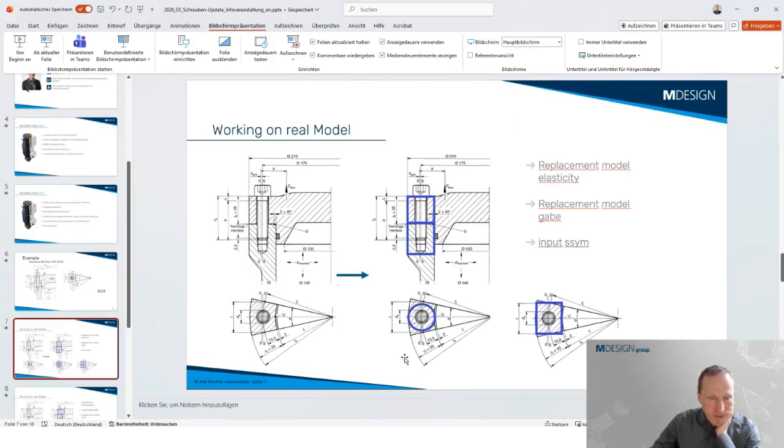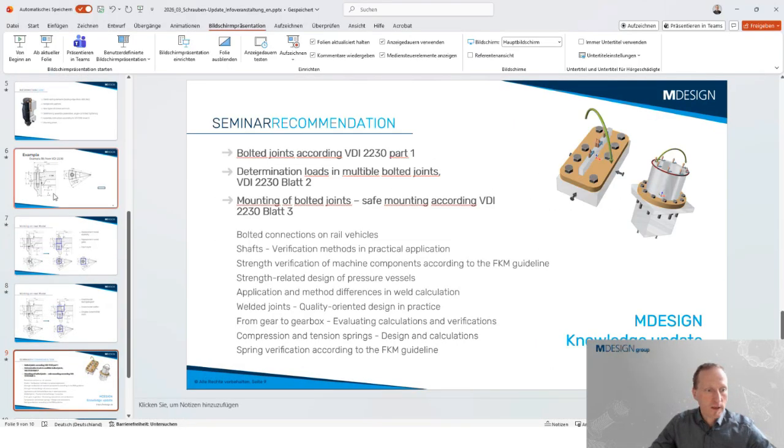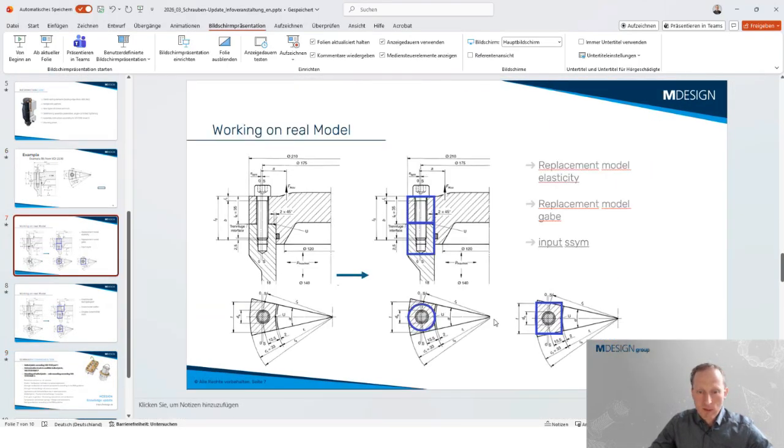The special example here from the VDI, B5, maybe I can discuss with you up to the calculation in 24. You must work with the VDI model. That means you must create a round geometry for the pressure cone, and you must create a rectangular geometry by the distance E. For the gapping, that's the no-gap case, that's a special calculation.